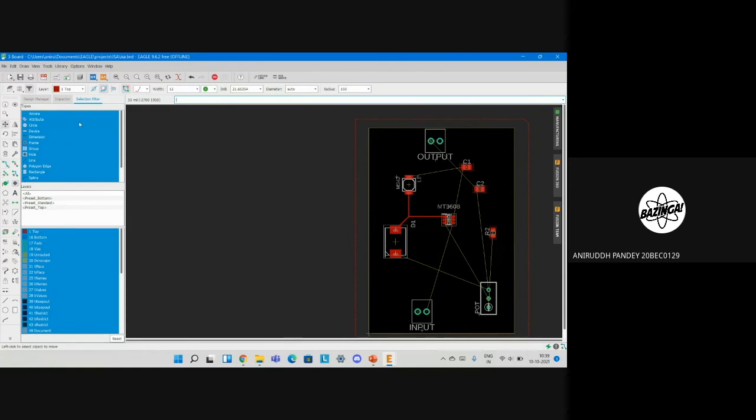Now I'll switch places with these capacitors. Also, this is going to be a better connection. Wires won't interfere with each other. And I'll rotate this potentiometer. Now we have a much better connection. Just again go to route. This capacitor is connected to the terminal. Done. Now this one has a connection with the potentiometer and the diode.